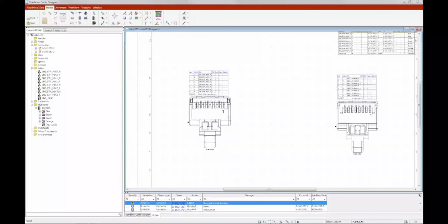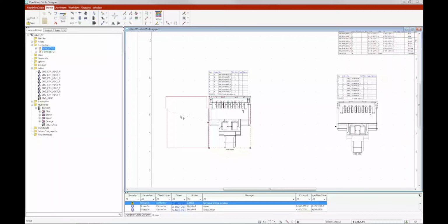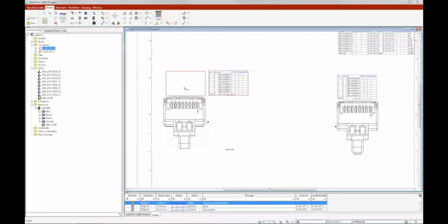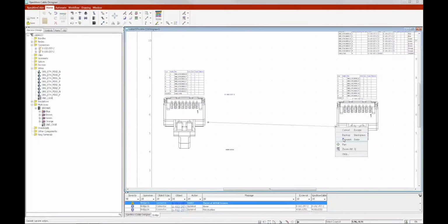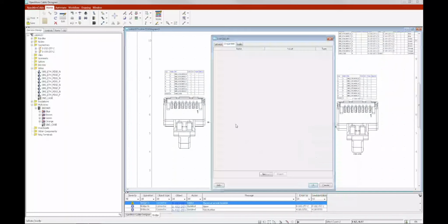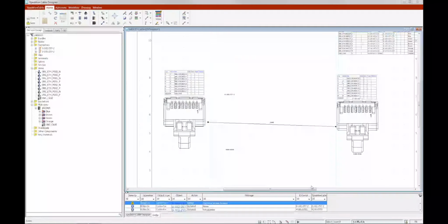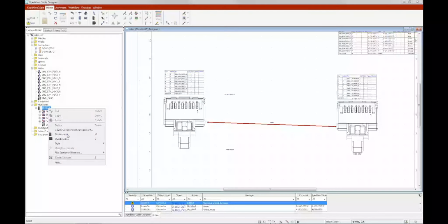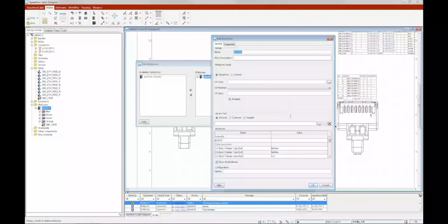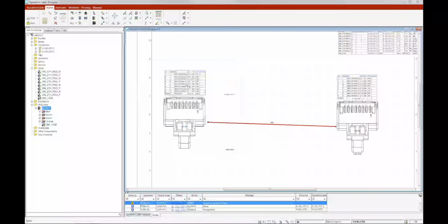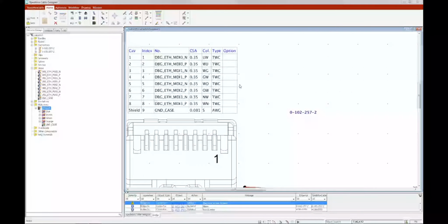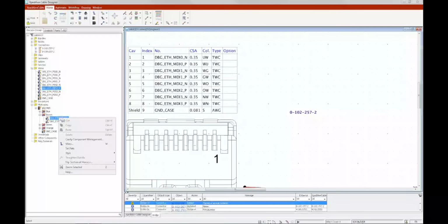In Cable Designer, wires are assigned to a bundle, so I first add a bundle between the connector nodes. Then, editing the bundle, the desired length is specified to 3000 millimeters. Multicores are predefined sets of wires, shields, insulations, etc. When a compatible multicore is assigned, wires are automatically assigned, and you can see the cross-sectional area has been assigned along with the TWC wire specification.